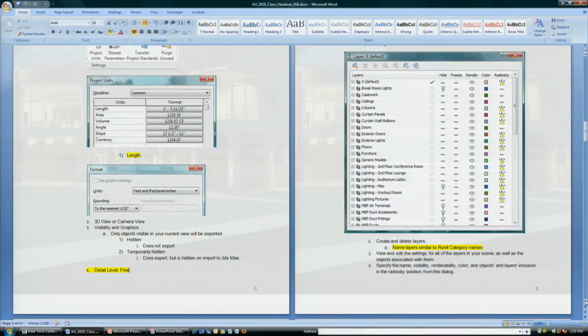So I had all those FBX files transferred out, and I'd come in and make the appropriate layer inside the layer manager in Max, and then I'd import that FBX information and merge it into the scene. Okay, so I've named the layers similar to Revit category names. And the reason I say similar is there are instances where after I start storyboarding that I really need to refine what's on what layer. So at that point I start breaking them down further.